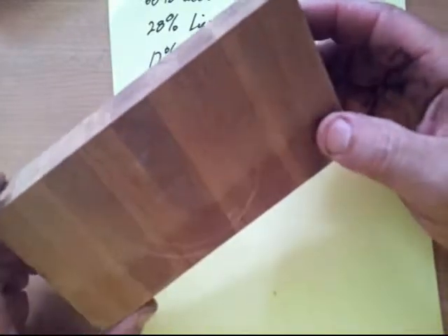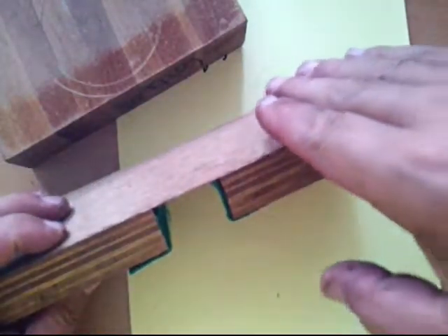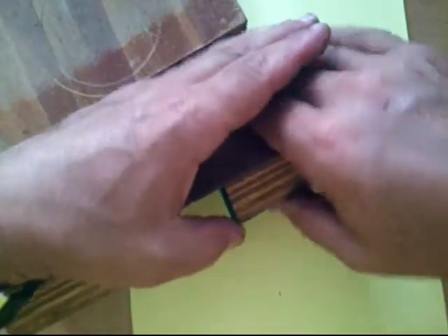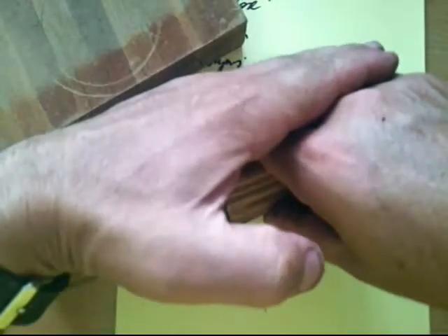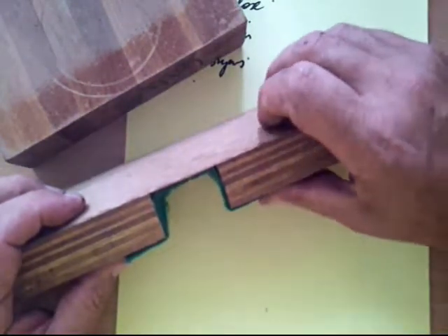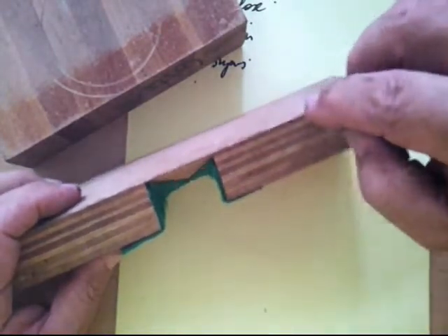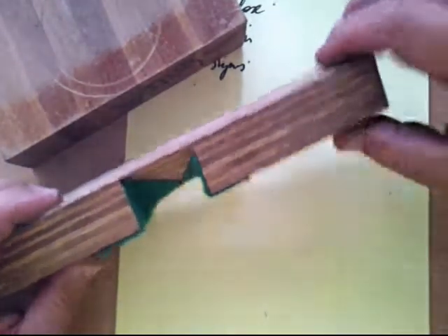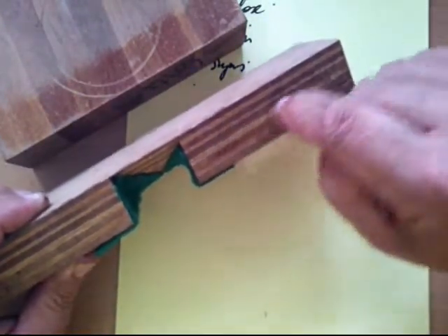It is very aesthetically pleasing though. So the options here for composites: wood itself is a composite structure, but for creating building materials out of composites, wood composites are laminated beams, like these ones here, and you can also form plywood. Plywood's very useful because it solves some of the anisotropic properties of wood by putting plywood sheets with the grain direction in opposite senses. So the grain direction moves one on top of the other at 90 degrees. That means that it starts to have very consistent properties in compression and in tension. That's one of the reasons why plywood is very useful.